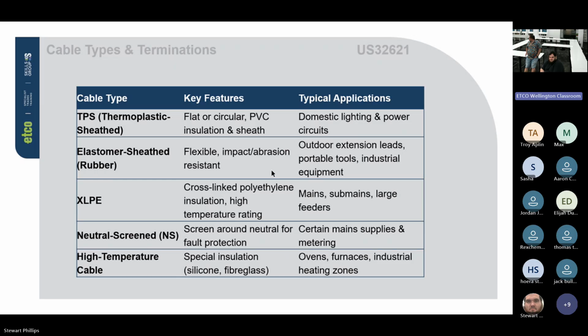But why would minimum bend radius be important? What happens if we bend the cable too sharply? Don't do that. That's not cool. That creates fires. So your high resistance is going to cause hot spots.